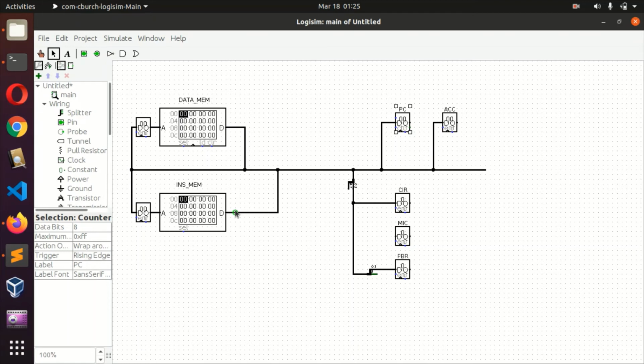So as a result, we need some kind of control, so that only one element can output to the bus at a time, not both. And what we will use is what we call the tri-state buffer, or the control buffer.